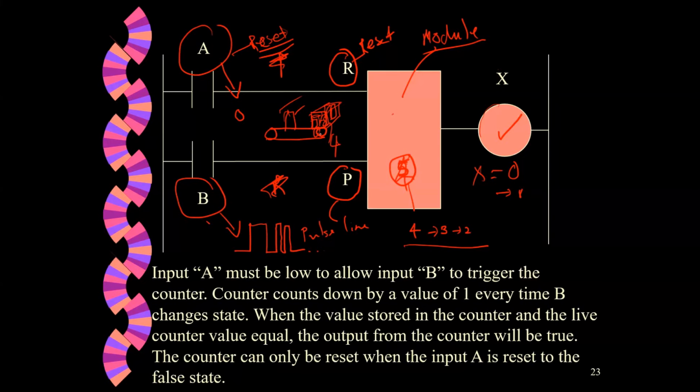Let's assume I want this conveyor to index by turning on the output until another sensor stops the conveyor. So this 4 triggers this, and the next one, a little distance away, will stop the pallet from moving any further, giving the next set of cartons room to be put on the blue pallet. So this is a packaging line.